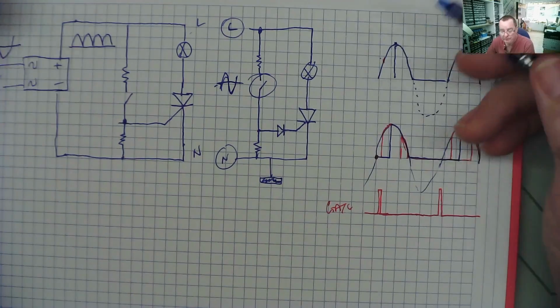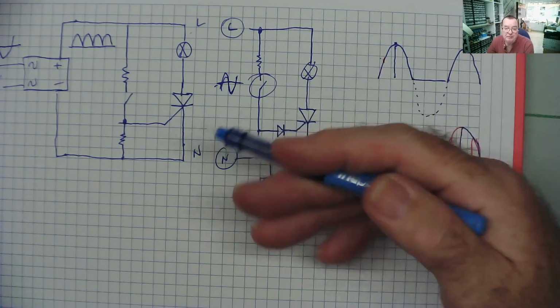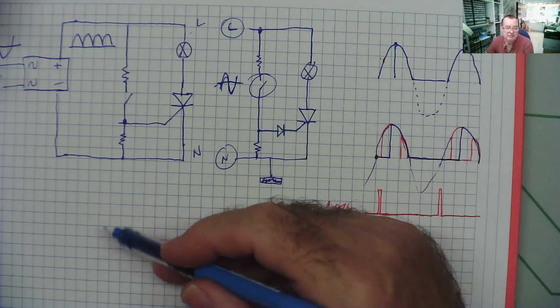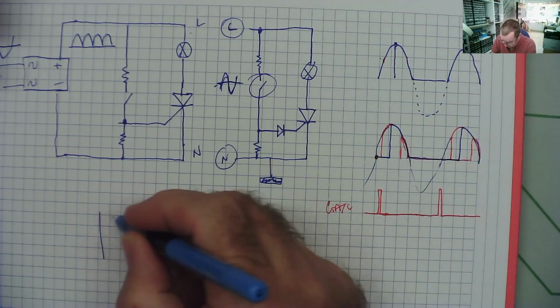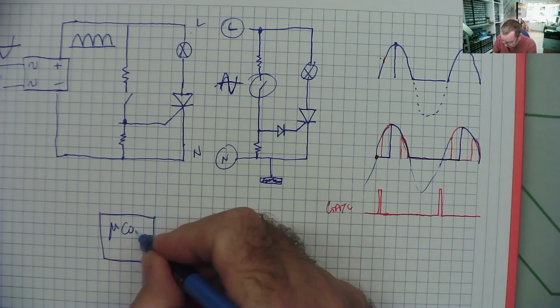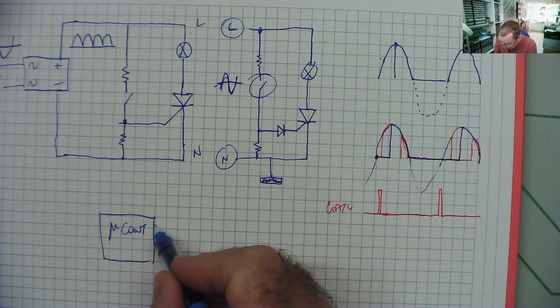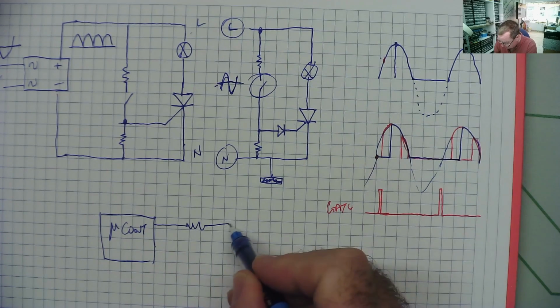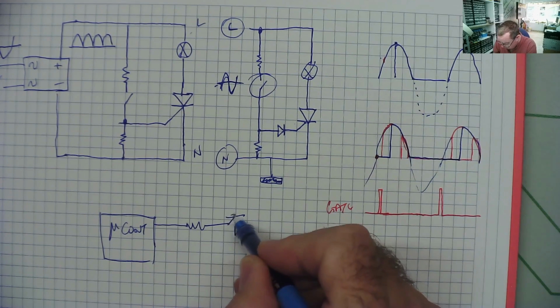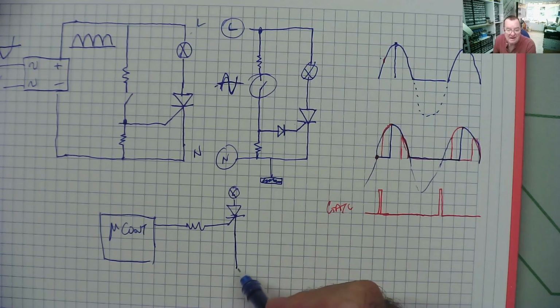Now normally the control circuit would be something like a microcontroller or something similar, which is on safety ground, and you can't connect the safety ground of your microcontroller, your Arduino or whatever the chip is, microcontroller. You can't use this effectively to send a signal into the gate of your thyristor. And the reason being, as I mentioned, that this end is hot ground.